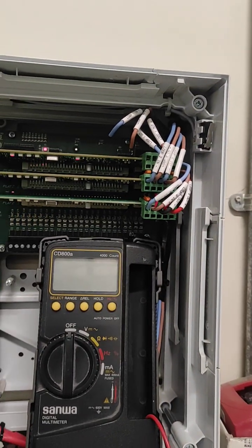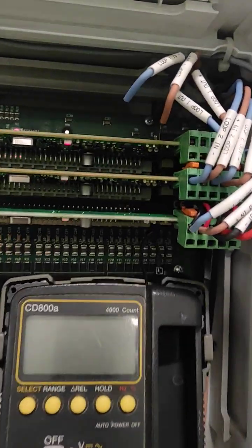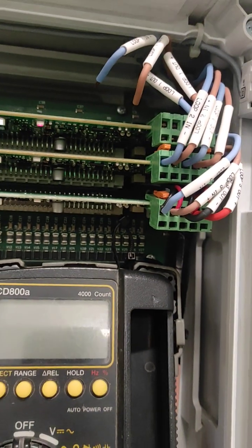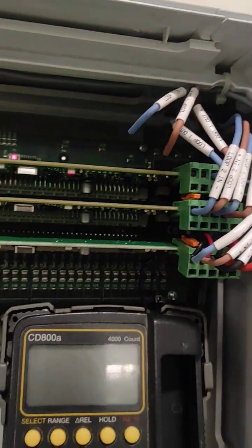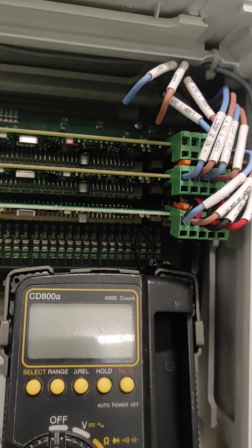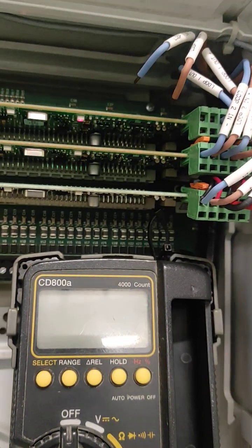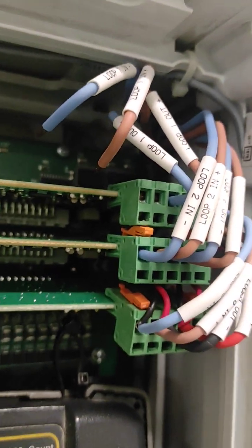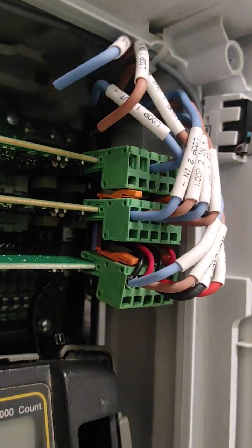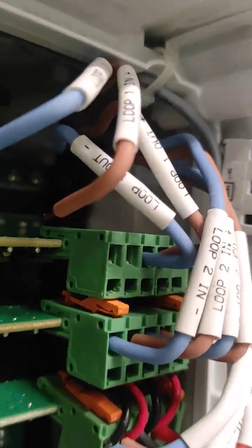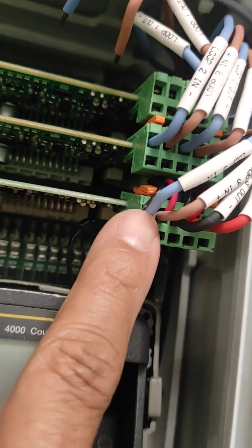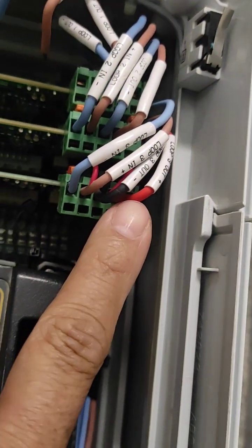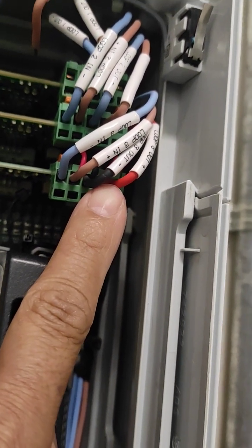I'm waiting for the guys to bypass one of the devices, because from device 41 it will open to device 42. We already replaced number 42 and the cable, but it's still the same, so we will bypass number 41. There is a voltage of 20 volts, but maybe the current is very small. That's why it will open at number 42. This is the loop in, the return cable from the last device, and this is the loop out going to the first device.